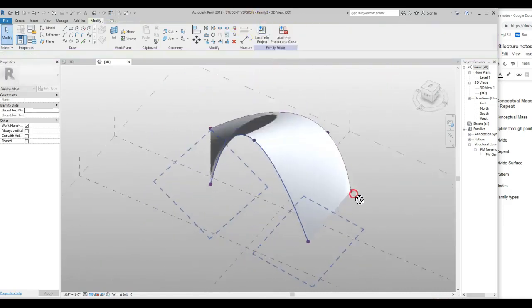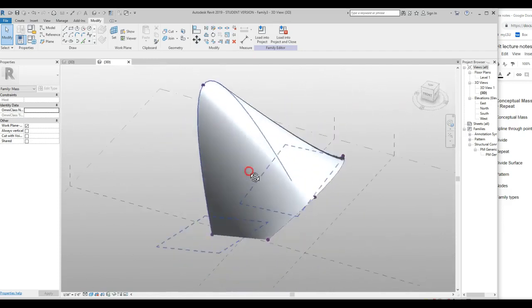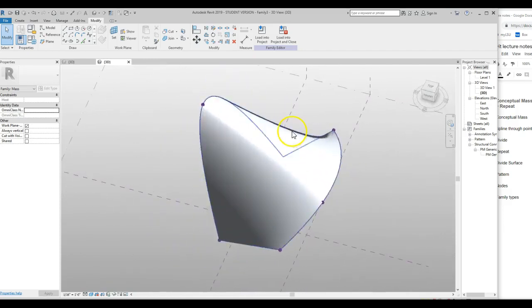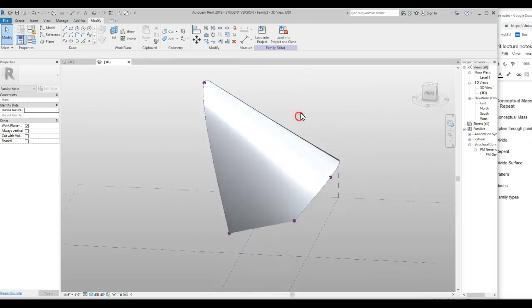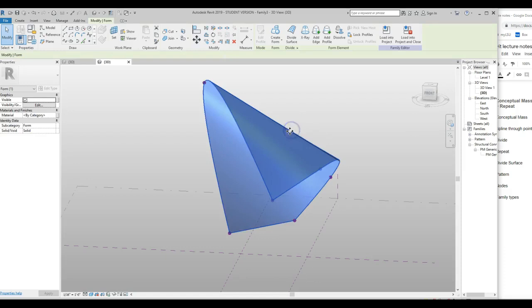Automatically creates a surface between these two. Okay. Now I'm going to grab the surface. Sometimes it's hard to grab the surface because if I grab this edge, it's grabbing the line. But if I grab where there's actually an arc anywhere, it grabs it pretty easily. If I'm over on this side, I can tab through the line, the object. There's the surface. So hitting in the middle sometimes doesn't do it, but that does it pretty quick.